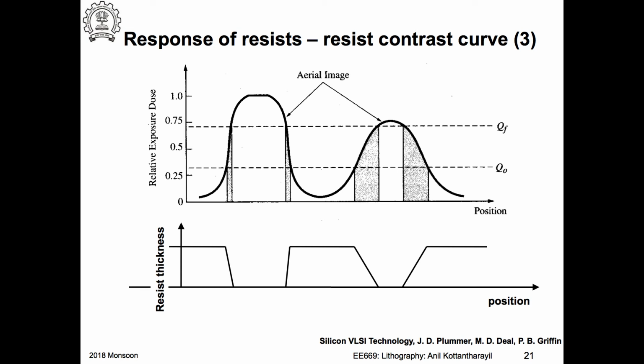So liftoff is something that we have already seen. Okay, but now suppose I want to use this resist for ion implantation. Yeah, ion implantation. Okay, let's just come back to this liftoff process. What would be an ideal resist profile? Ideal resist profile, if I want to guarantee liftoff.